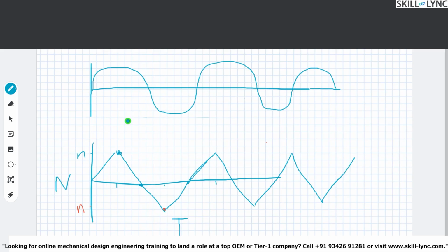So in a constant amplitude study, at 10 seconds for this example, we had n. Again at 30 seconds, we had n, but in the different direction. So it was either an extreme value in a certain direction or an extreme value in the opposite direction. But in a harmonic study, we will be gradually increasing the load here. So let's say from 0 to the maximum value, we're not going directly from 0 to 100.